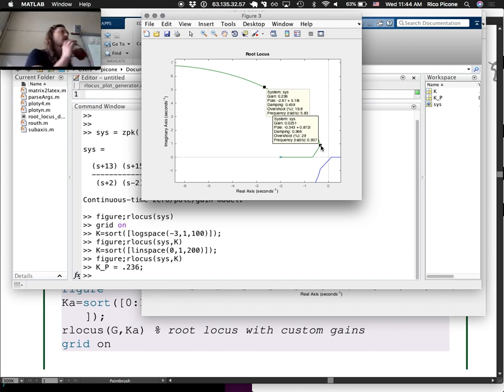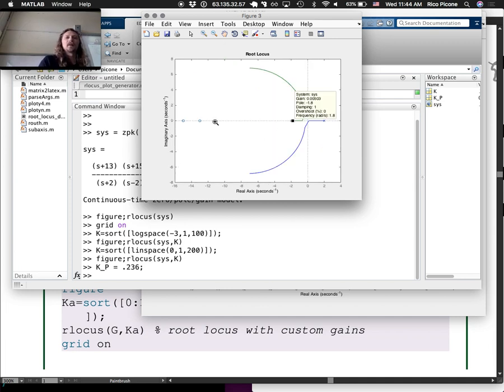As far as assuming it behaves like a second order system, would that only matter if the two points were a lot and had huge distance between them? It won't behave like a second order system if you've got closed loop zeros that encroach on this area too much.